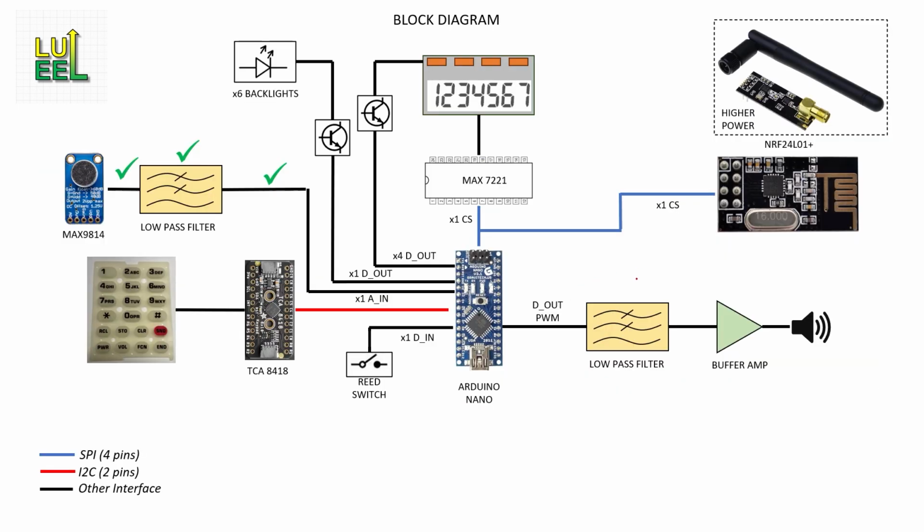But before I can do that, there's one final chunk of hardware that I need to insert into this chain. It's another low-pass filter and an audio output amplifier. The filter is necessary to remove the PWM carrier frequency and smooth out the remaining signal. The amplifier isn't strictly necessary. You probably could connect earbuds after the filter and likely get some audio response, provided they weren't low impedance earbuds.